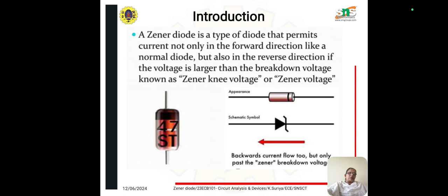Some Zener diodes are used where high levels of power dissipation are required. The Zener diode which is the most commonly used is contained within a small glass encapsulation having a band around one end, marking the cathode side of the diode. There are two tags at the end of the bar in the circuit symbol of the Zener diode, one in the upward direction and the other in the lower direction. So in this way we can easily distinguish between the Zener diode and other diodes.